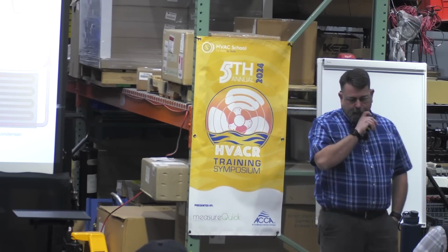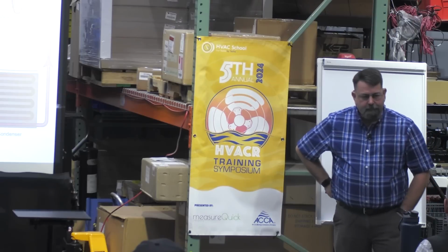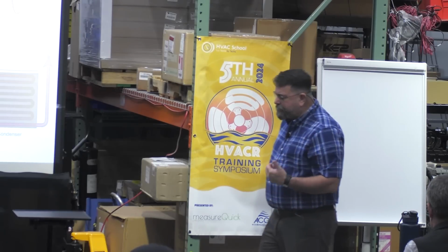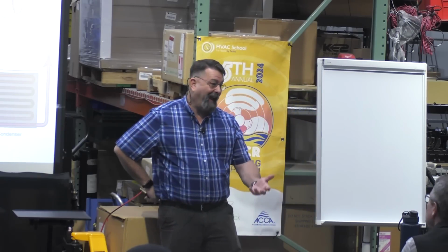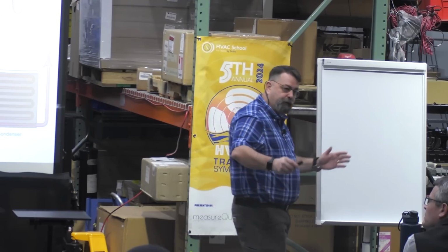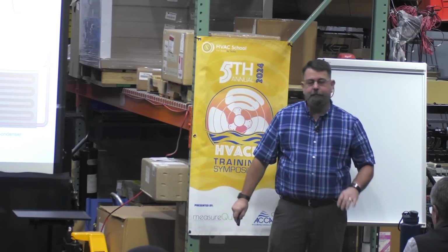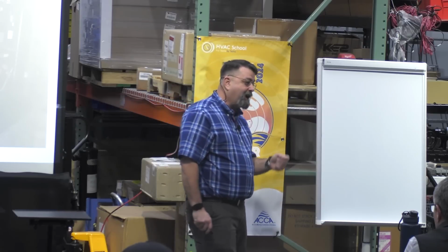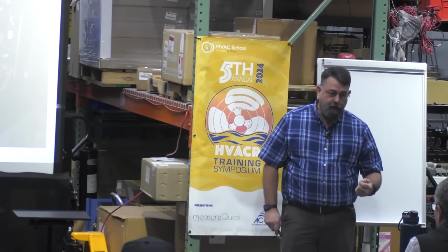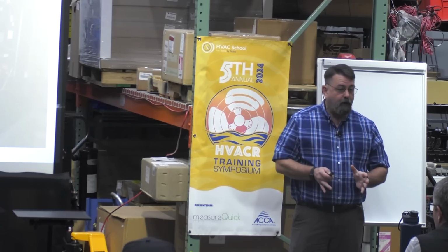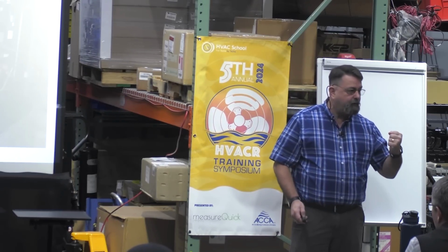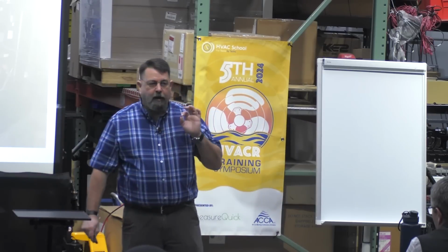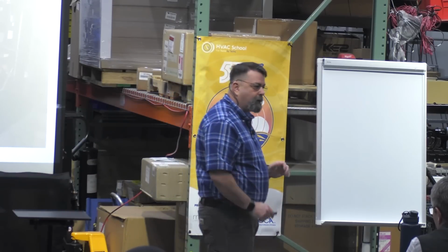Sir, case circuits, do they have to be made up of similar temps? Exactly, right. So the rule of thumb engineers use is they're going to be exactly the same case, right? They may be 4 foot, 6 foot, 8 foot, but they're going to be exactly the same. Practically, does it have to be? Not really. Practically, it needs to have the exact same temperature evaporator, and it has to have the same defrost schedule. So I'm going to turn that refrigeration off and run electric heat or hot gas or whatever I'm going to do. So I need the defrost to line up, right?